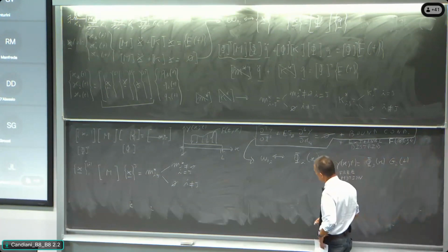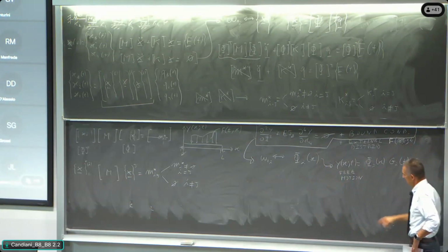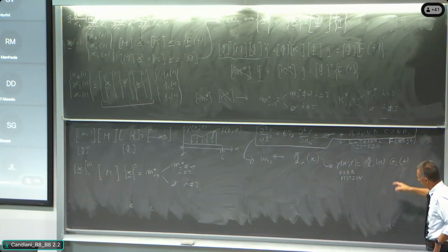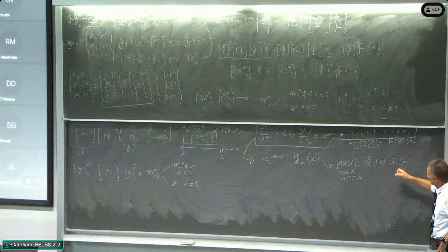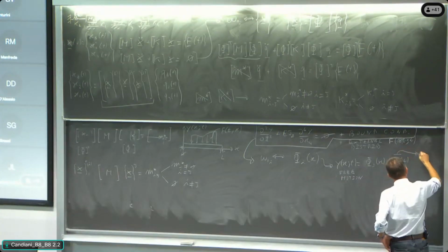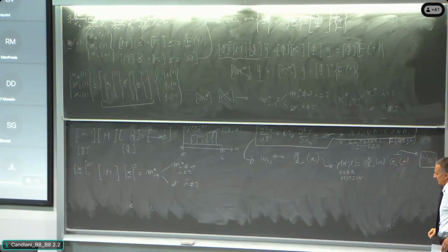And studying the free motion, we understood that attaching the boundary condition to the partial differential equation, we write the free motion as the superposition of the functions that are the eigenfunctions of the problem, multiplying a time-dependent harmonic function that is running at a frequency that is very specific of the mode, omega 0i. So we are studying the free motion problem with boundary condition.